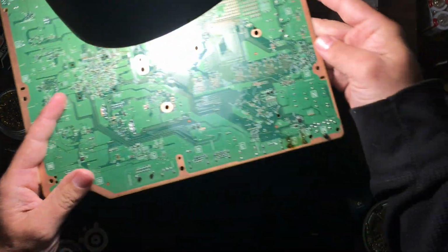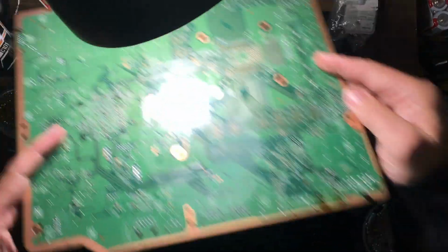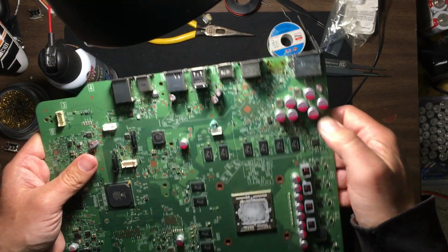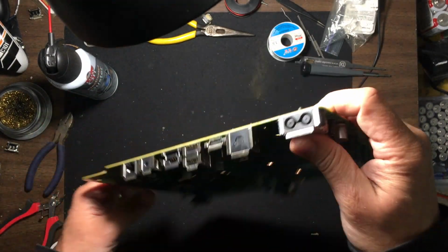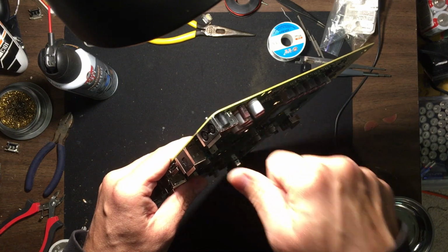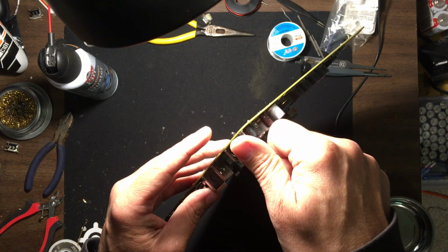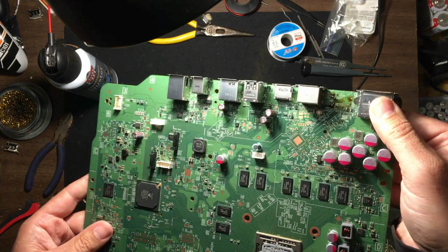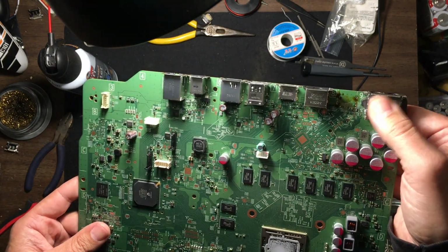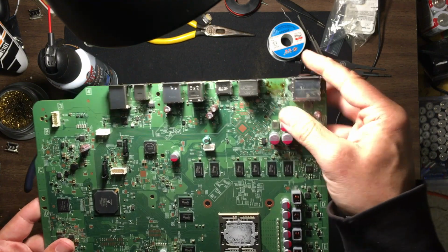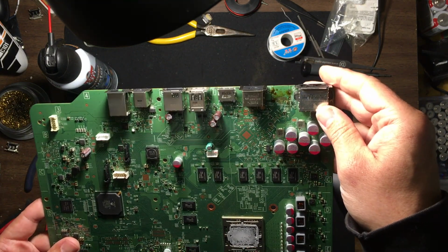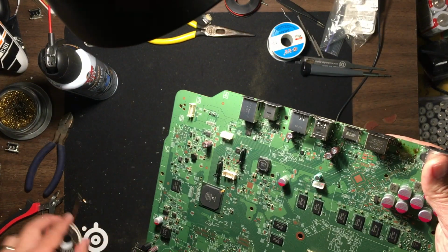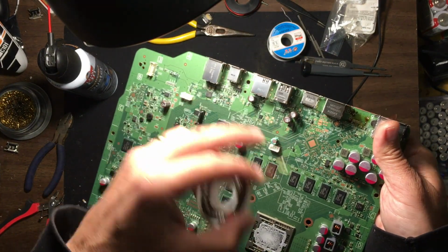But now it looks a little burnt. That's the flux. So after, I forget where I left off, but I had the pins left in there, and basically I put the board on its side, used the pliers, pulled, and just applied heat, let it sit for a little bit, wiggled, and pulled it out. And then once I got all those out, it was a matter of actually clearing out the holes here for when we put the new port down. And to do that, put a lot of flux, use your desoldering braid, and keep going.